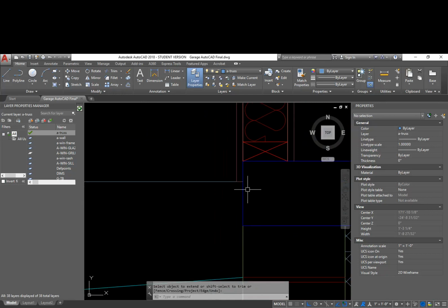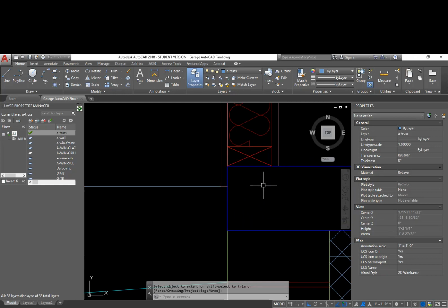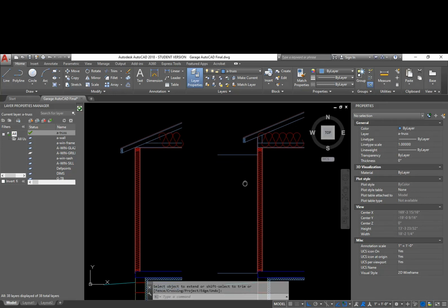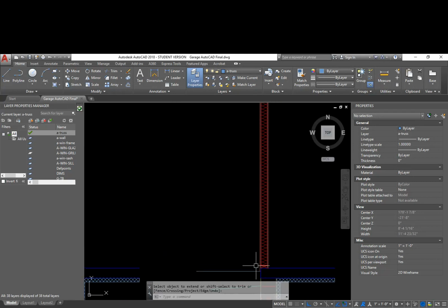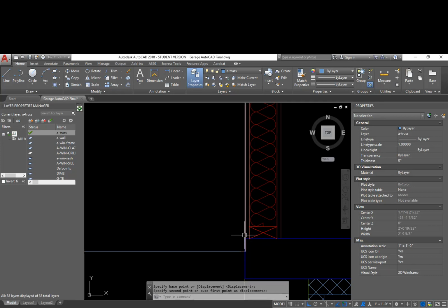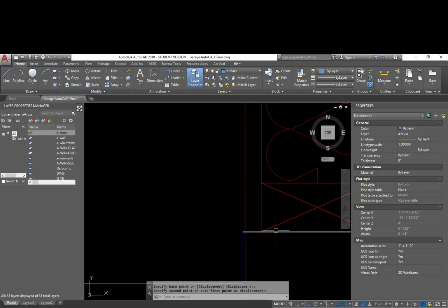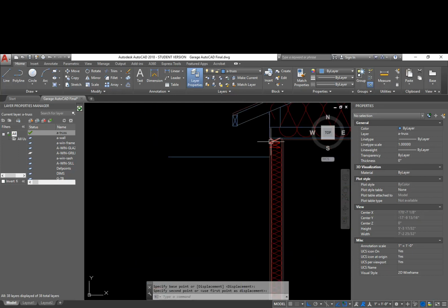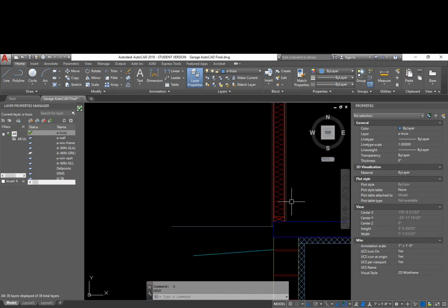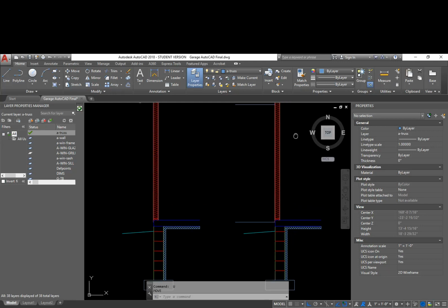Now if I could do the same thing down here, extend this past even further and secure this to this slab, or if this would be a wood structure, now all of a sudden I have my wall tied together with my floor here, and I have my wall tied together with my roof here. So it's a very smart way of laying this out. And I don't see a whole lot of contractors doing this. What they'll do instead is they would have this whole thing sitting back a half an inch so that my OSB lands right here, which is going to cause a problem with the water wicking, but it gives them the option of ending this with an 8-foot piece of OSB. So this is something that you have to call out in the drawings and show that.